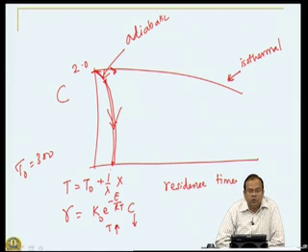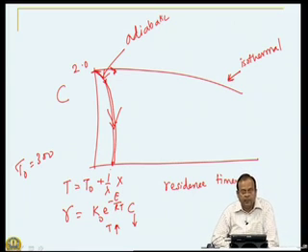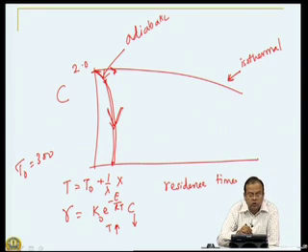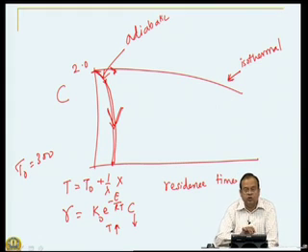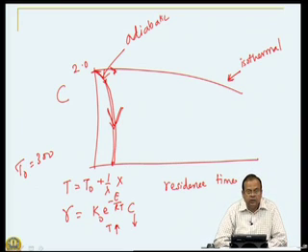Now, you will start appreciating what I had said some time back, why adiabatic operation is important. Remember, this is almost like an uncontrolled reaction, because the slope is almost infinity. So, you do not know what will happen if such situations arise, and therefore, knowledge of adiabatic operation is important.